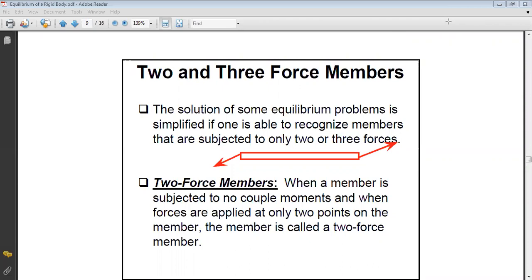And what also? Look, I will give you an example. These are two equal and opposite forces. Will your system be in equilibrium in this case? Why is it not in equilibrium? Because the first condition of equilibrium, sum of forces equals 0, is satisfied. But the second equation, sum of moments equals 0, is not satisfied because two opposing forces will give you a couple.